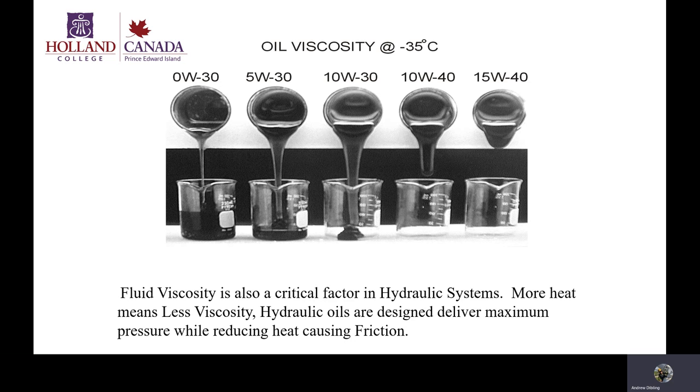So a lot of hydraulic systems will have cooling devices and heaters to keep that oil in the right viscosity to make sure that it is able to provide power in the most efficient way possible.